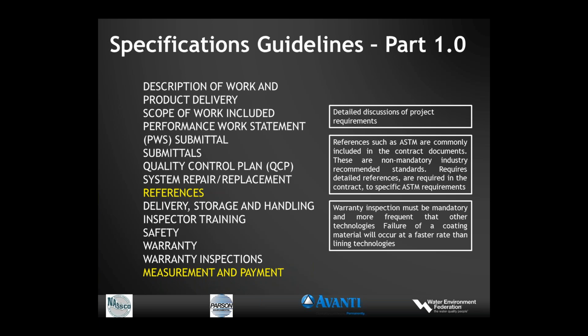And the common thing we need to understand with coatings is if a coating is not monolithic, meaning it completely covers the structure like a shell, if there is a defect or a pinhole, then the corrosive environment can get through that pinhole, can get behind the coating, and once it gets behind the coating, then it actually accelerates the deterioration of the manhole. So it's very, very important that these projects, once they're completed, are effectively reviewed again